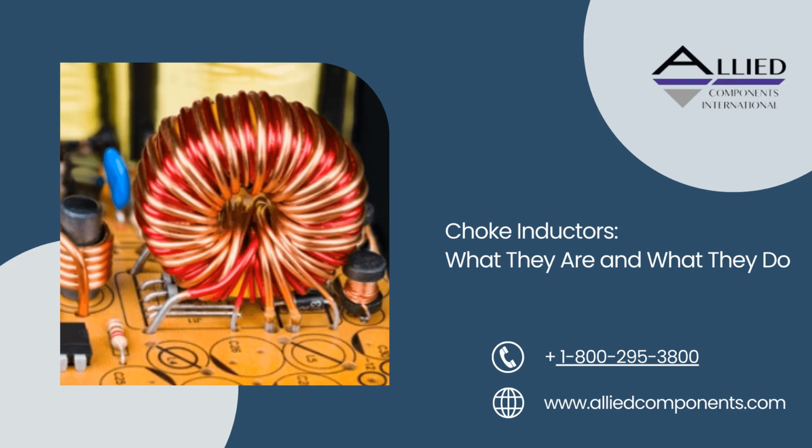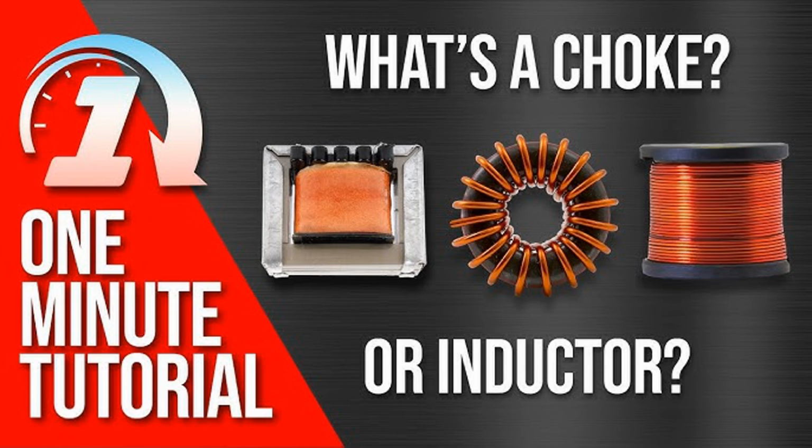Example of operation in a lawnmower. In a lawnmower equipped with a manual choke, when the engine is cold, the operator pulls the choke lever to engage it. This enriches the air-fuel mixture by limiting airflow. After starting the engine, the operator gradually opens the choke as the engine warms up to allow more air in